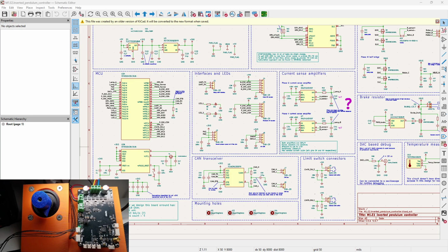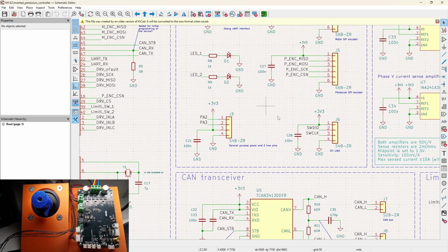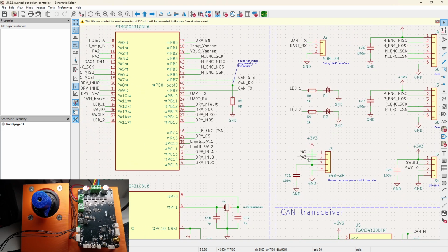That's going to be very useful for the future. Because when you are done with FOC implementation and you are confident in your current vector forming and your voltage vector forming, in your feedback from an encoder, when your control loops are running, the main limiting factor you have to work with is actually motor temperature. So the suggestion is very nice, and it's currently not supported by the PCB in the way it is implemented now.